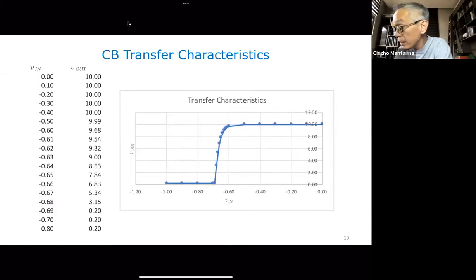So this is my saturation. I did not show here that this goes down. Theoretically this will go down, but let's just say that the diode voltage becomes about constant at about 0.7, even if your input is greater than -0.7.